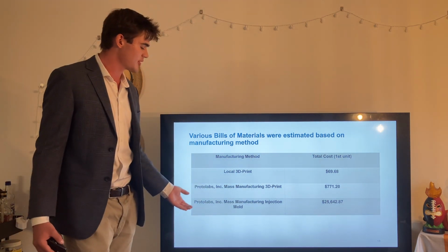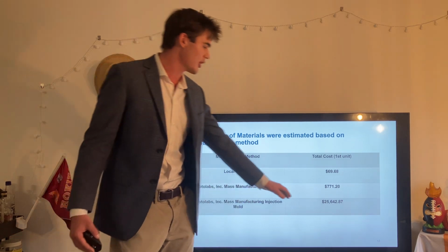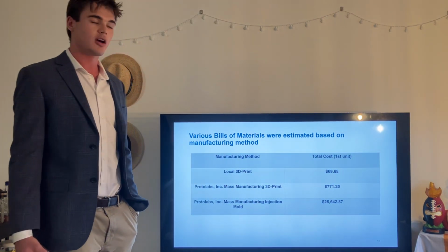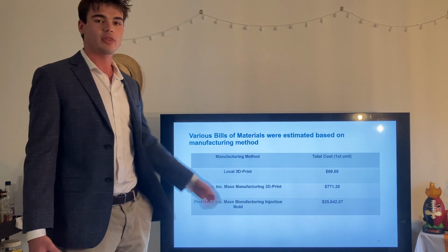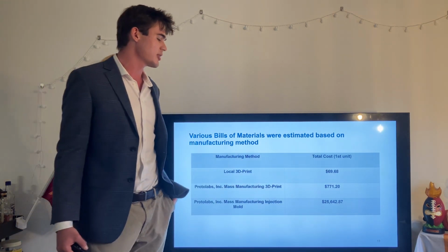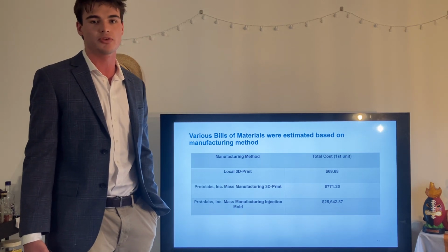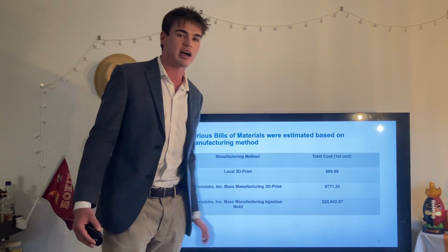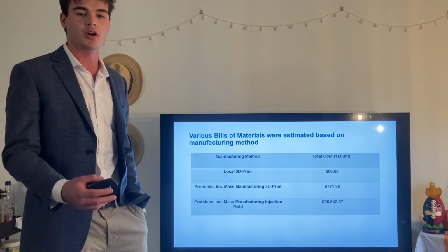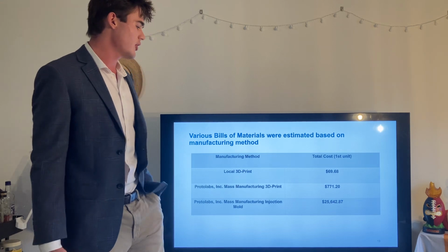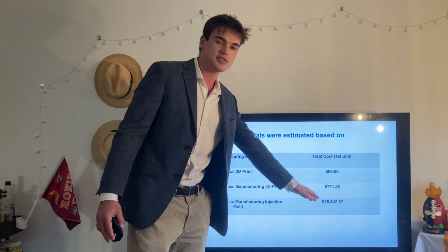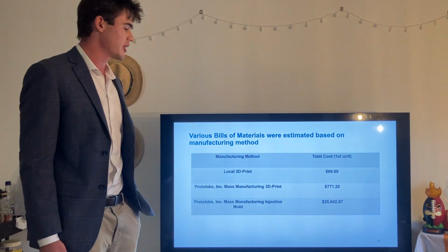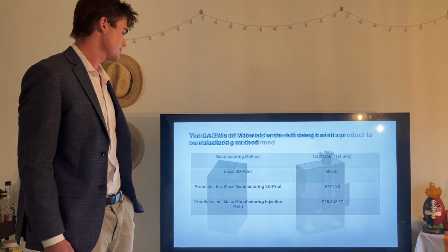Finally, Protolabs also gave us quotes for injection molding, and the initial cost for the first unit is extremely high at over $25,000. However, for injection molding, that cost is mostly the extremely high front-loading cost of creating injection molds, and it is much likelier that the cost would drop exponentially over time as the molds can be used over and over again. And so, even though our break-even analysis would likely skyrocket into the thousands or tens of thousands of units to break even, after that number was achieved, we would experience profit much quicker than the other 2 methods.